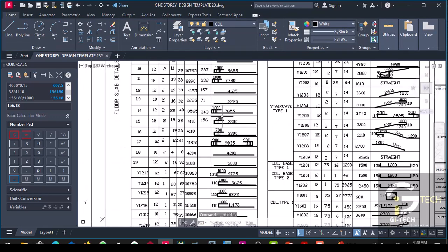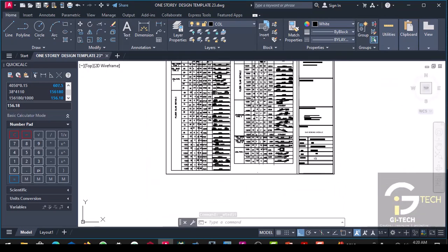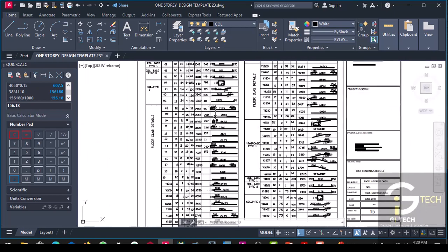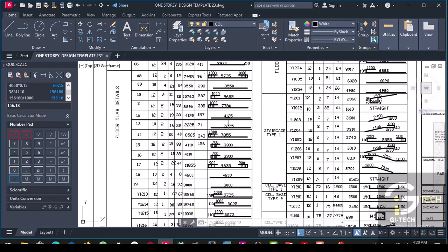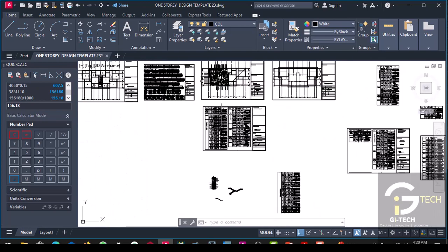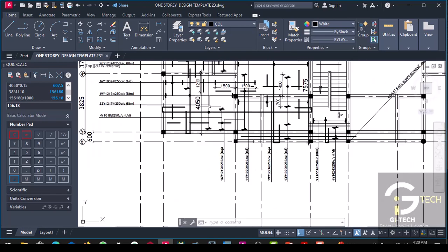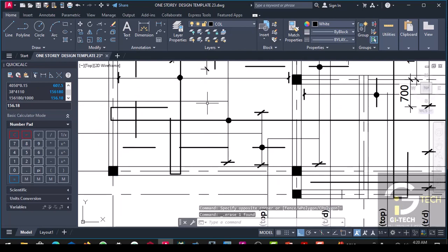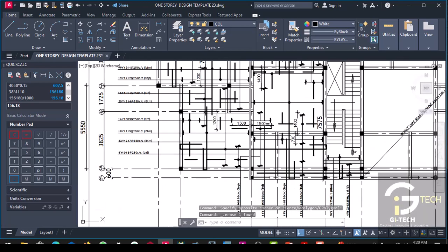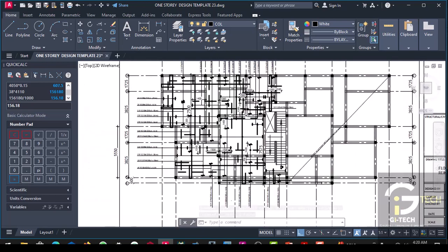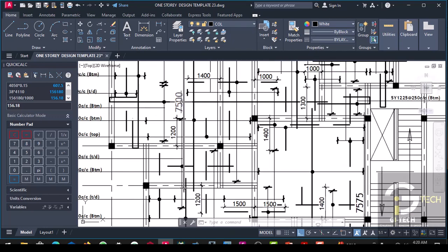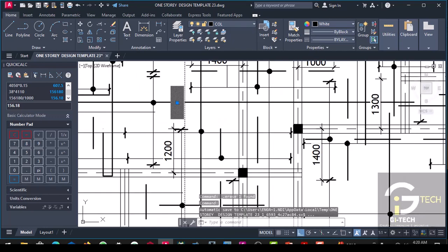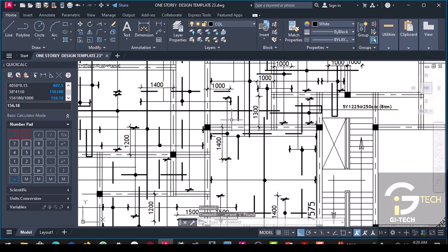Okay, so this is basically how to calculate a bar bending schedule in a slab. I think with the extent that we have gone, you will be able to finish the remaining part of it. You use the same approach. We have identified all the shapes: the L shape, the straight shape, and the U shape, where you have the returning bar on both sides.